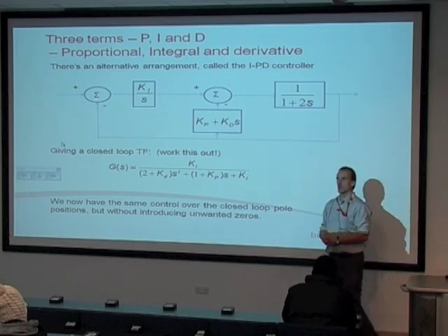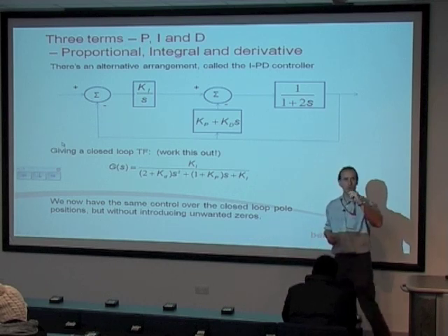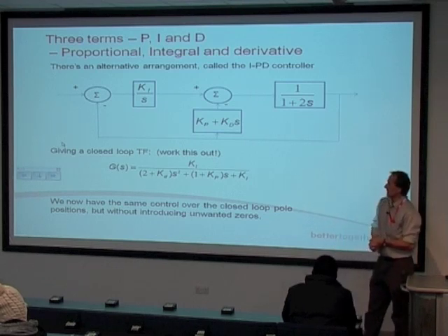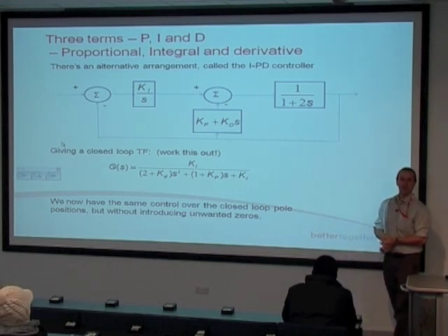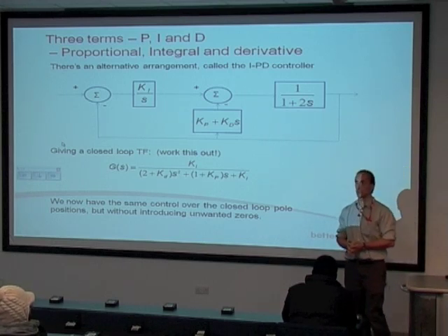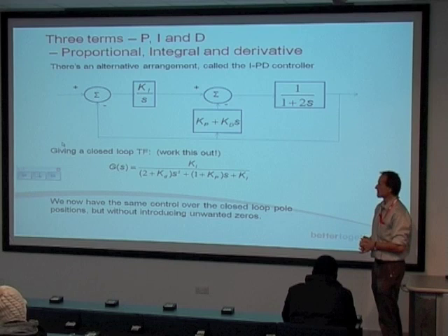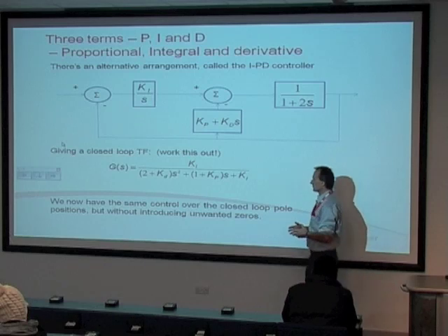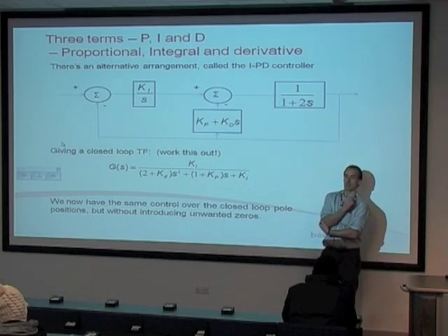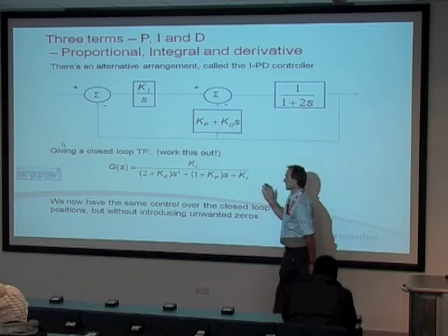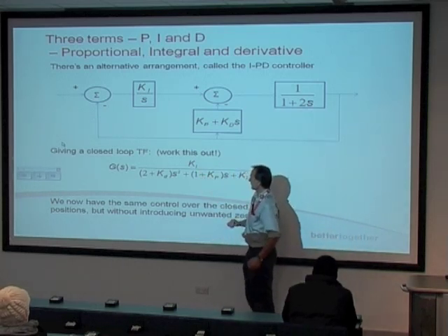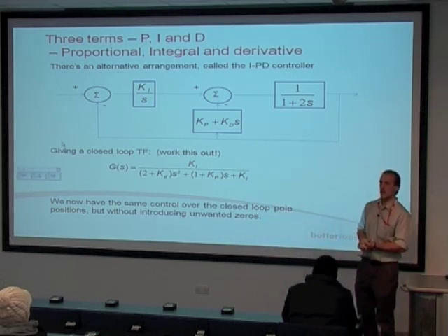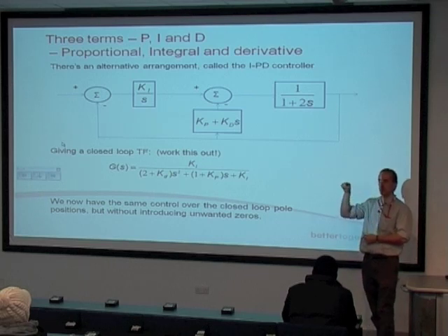Now there's several ways of doing that. I was kind of hoping one of you might have come across 3-term controllers, depends what industry you're in. There are what they call empirical methods for doing this, which I'm not going to talk very much about. But there are a number of different empirical methods that rely on semi-experimental techniques. For example, one technique might say you make Ki and Kd 0, and you start winding up Kp until the system just oscillates.